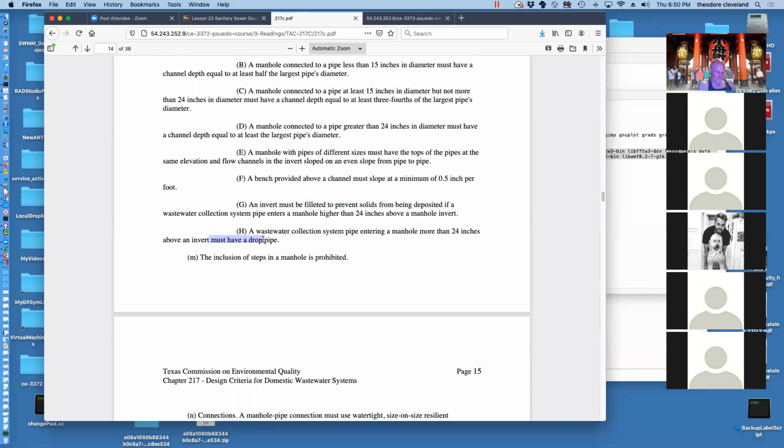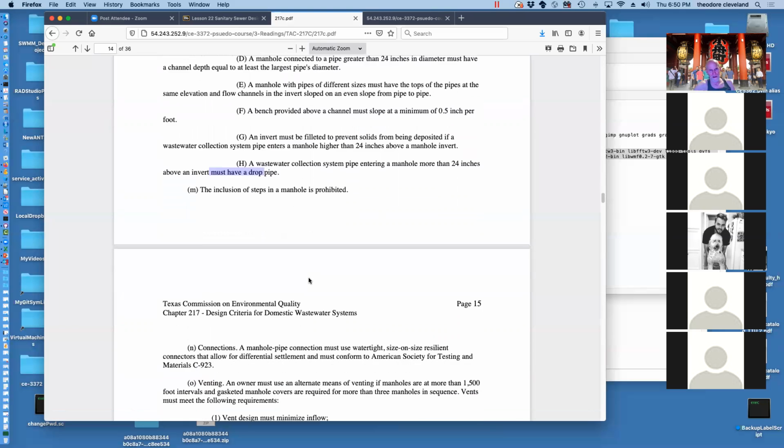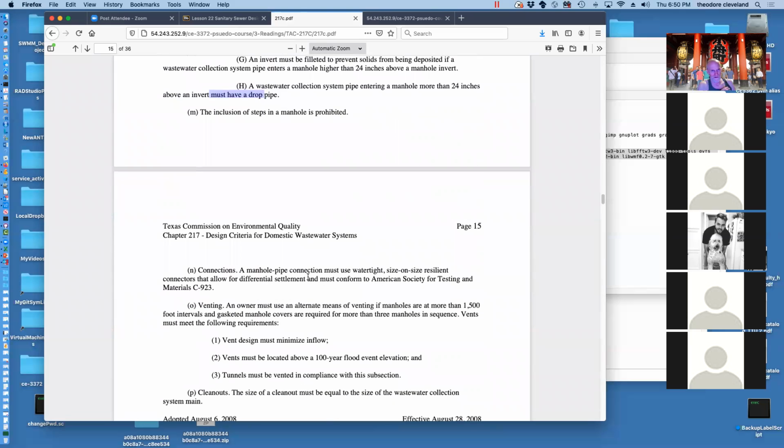And so they made the 2-foot requirement not necessarily for hydraulic reasons, although I'm sure there's some, but literally if you're in the maintenance hole and sewage is coming in greater than 2 feet off the bottom, it's going to hit too high on your body and fill up your waders with sewage. And you'll have the ultimate example of poopy diapers in that case.